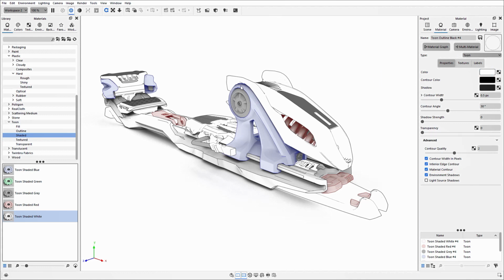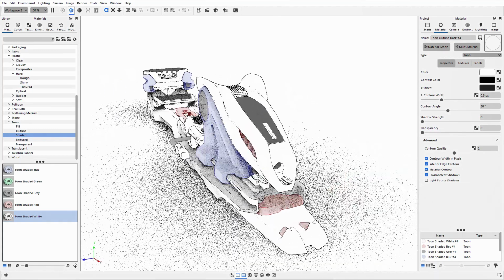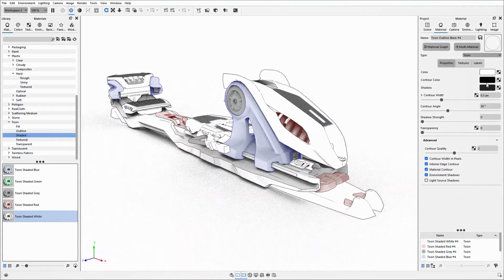The contour color controls the line work around the outside. So again, you can manipulate what colouring you want that to be using this colour block within here. Regarding the thickness of these lines, that is controlled by the contour width. So here with this parameter, I could increase the value if I wanted that line work to be a bit stronger for this part of the model.